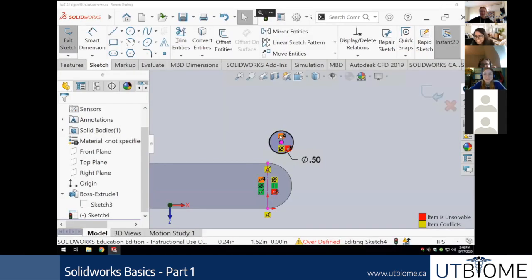What is this? Welcome to SolidWorks. So what has occurred here is something called over-defining. You have to define stuff perfectly in SolidWorks. If you give too many dimensions that are conflicting or unnecessary, then things start to break. So I see where things went wrong.